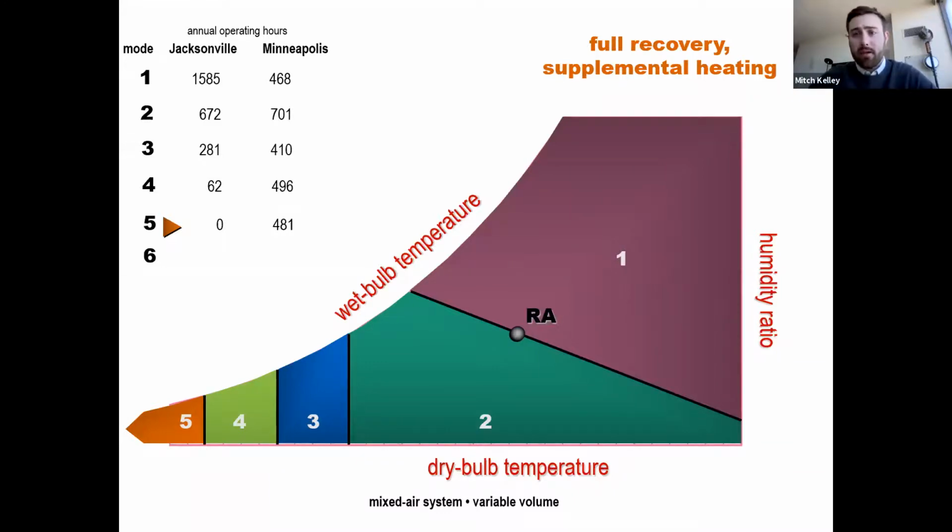Now, it's interesting with plate and frame heat exchangers, a lot of times their method of use dictates a higher level of maintenance, because usually when you see a plate and frame heat exchanger, it's coming out of some sort of diesel shop, an automotive maintenance facility, something with a lot of nasty contaminants in the air that you end up having to clean off more frequently from that plate exchanger. So it's not necessarily the plate exchanger's fault that you have to clean it more often, but usually in the applications where you use plate exchangers, you end up having a more rigorous maintenance schedule.